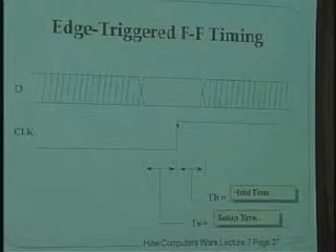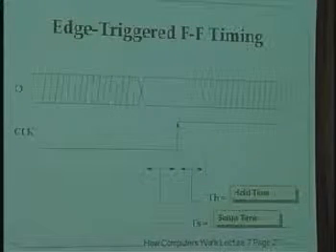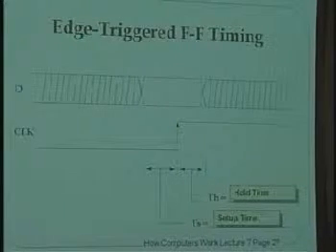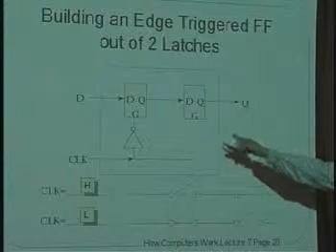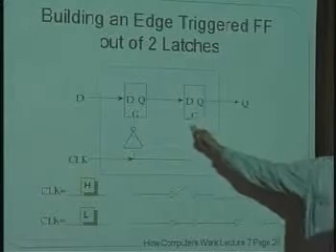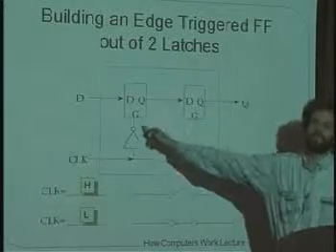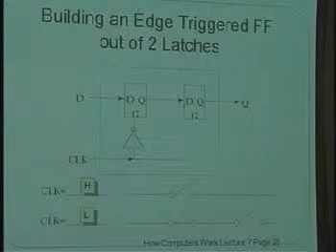Yeah? Does the fact that in one case it has to flow through an NOT gate and the other case doesn't present a timing problem? Yeah, it turns out that you have to be a little careful about the overlap of the two G's here, okay? And in general, you want the signal on the second one to happen a little bit sooner compared to the first one. And if you want to, you can work that out. That doesn't matter right now.